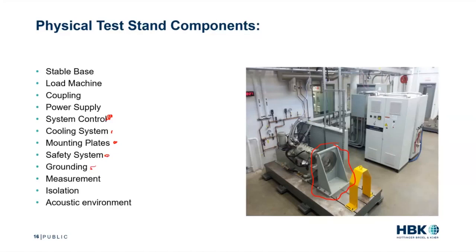Those are things that, again, probably get taken for granted. A really good grounding is going to make all your measurements better. Anybody who's gone through and run any of these types of tests knows that inverters are kicking up all kinds of electrical noise, and you don't want to be picking that up. So having a really reliable grounding system can make your life significantly more simple.